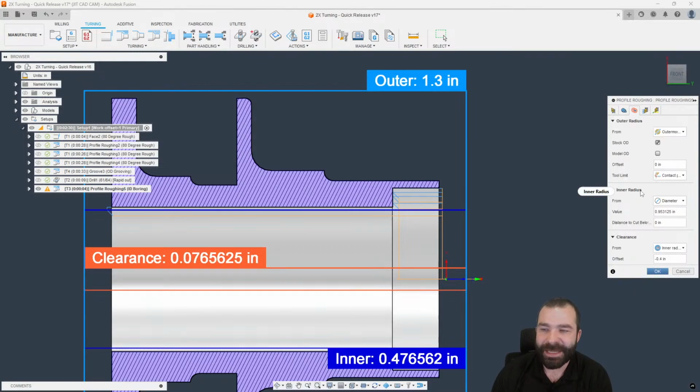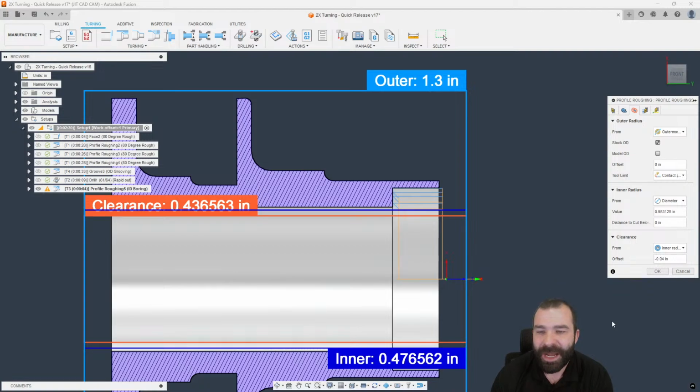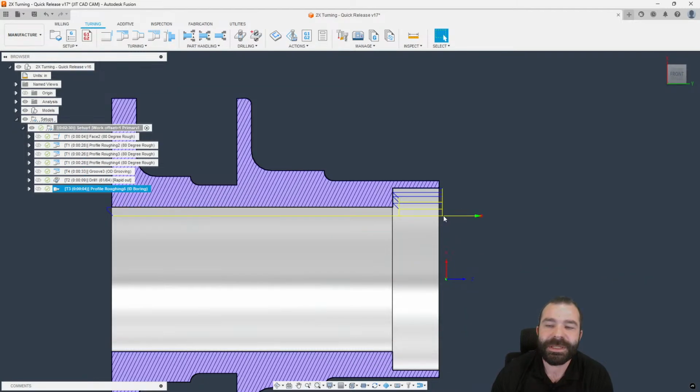And what inner radius is this guy right here. And now you've noticed this orange line has started to open up. With that, I'm going to go ahead and change it from 400 to 40. And now you're going to notice my blue line and my orange line, right? So my orange line is where we're always going to create our clearance from. And when I hit OK, you're going to notice my yellow line has now started much further out.